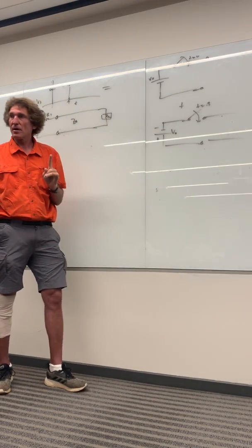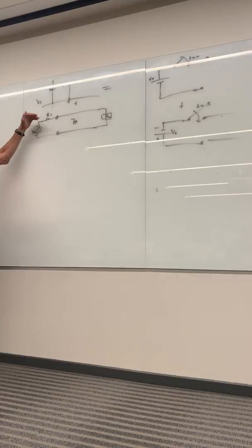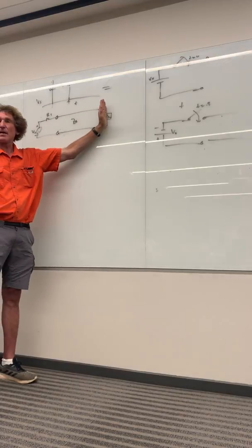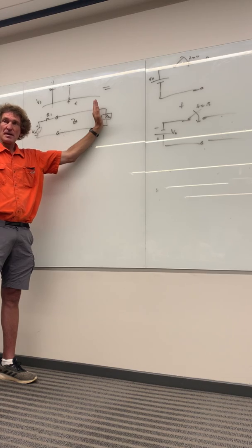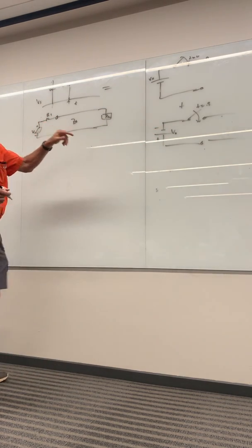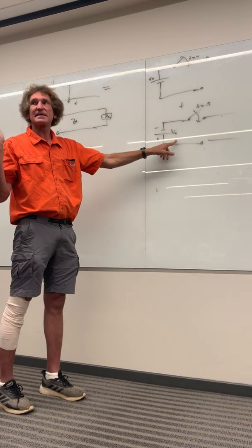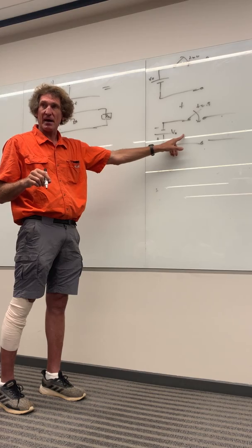Now, hear me on this one. This is like a constant voltage floating there, and you can get the bounce diagram at any point, right? We can get the voltage for this one. Do y'all agree with me? Now what we do is a time delay, and we say this one is going to have the exact same bounce characteristics, except they're negative and they're time delayed by tau.